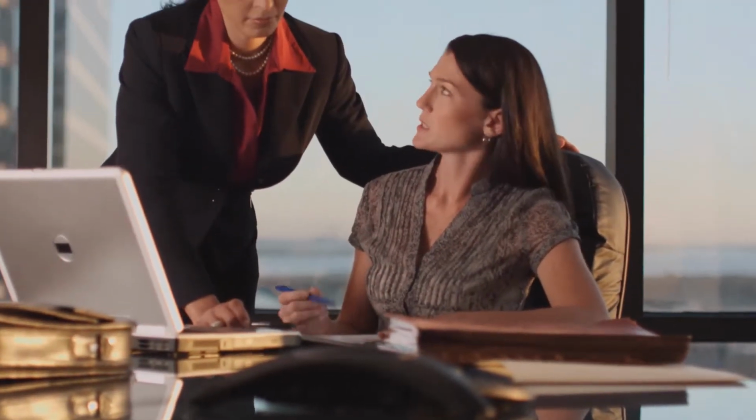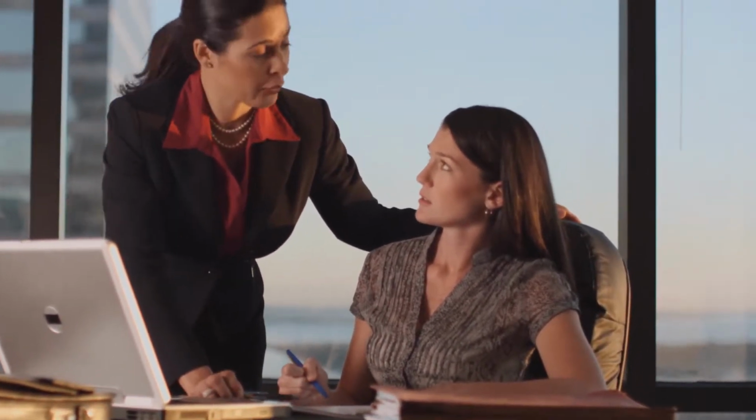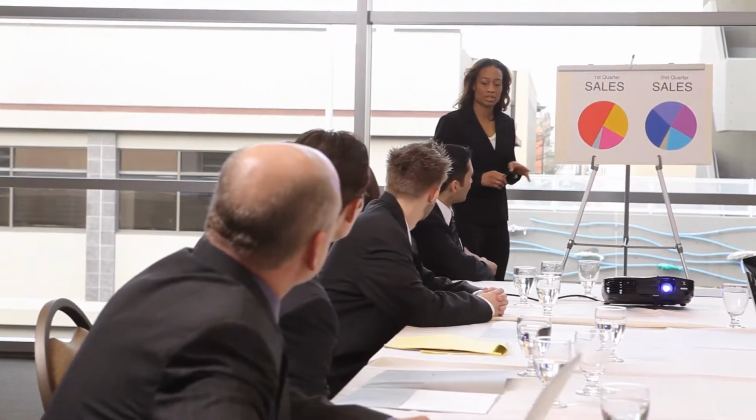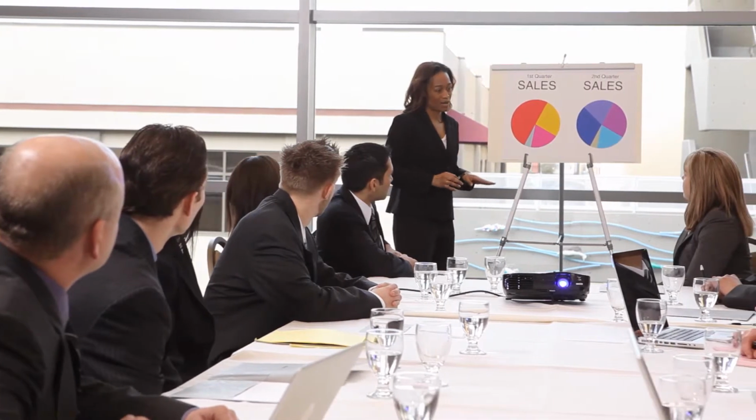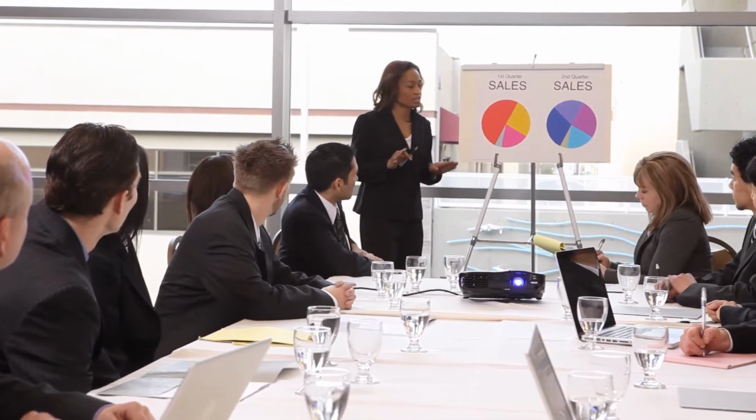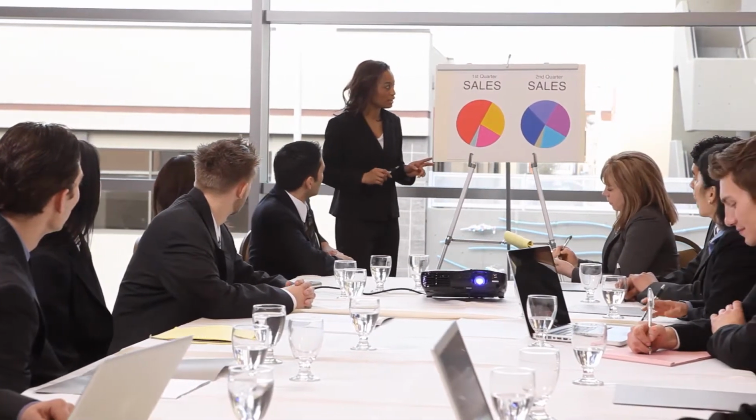Lighting is a great system to use for demand response. Since demand response reductions are short in duration, but usually come during peak day business hours, reducing lighting load to meet demand response goals has minimal impact on business operations.